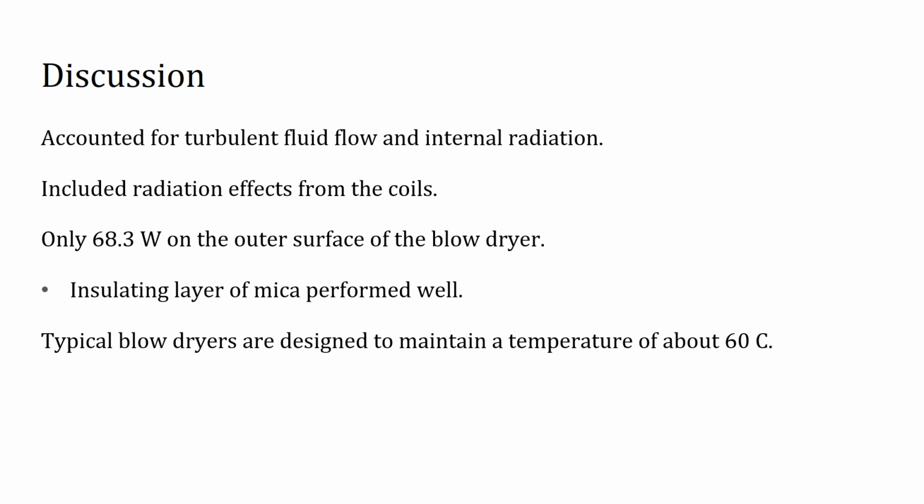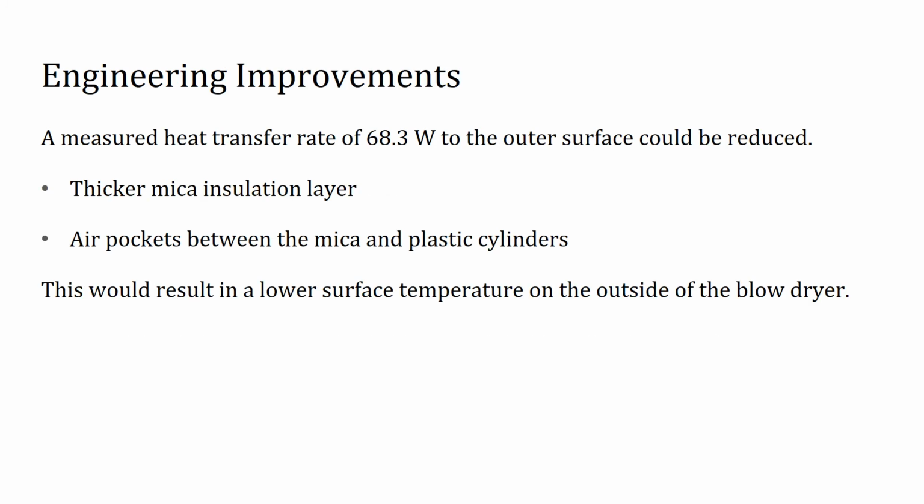However, typical blow dryers are designed to maintain an outer surface temperature of about 60 degrees Celsius to prevent burns to the skin. However, the surface temperature of our blow dryer was measured at 78.8 degrees Celsius after it had reached steady state conditions. By understanding the heat transfer rate through the blow dryer, we can see that improvements could be made to future blow dryer designs.